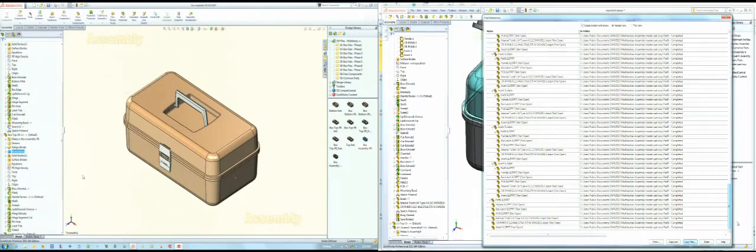Okay, so we see a little difference here. Now I have to get rid of these references, and you've got a couple of choices. We're going to kill the parametrics here, and we're either going to kill them permanently or we're going to think about resurrecting them. To kill them permanently means I'm just going to take this assembly, go into the parts that have the references, and blow them away and replace them with something internal to the parts.